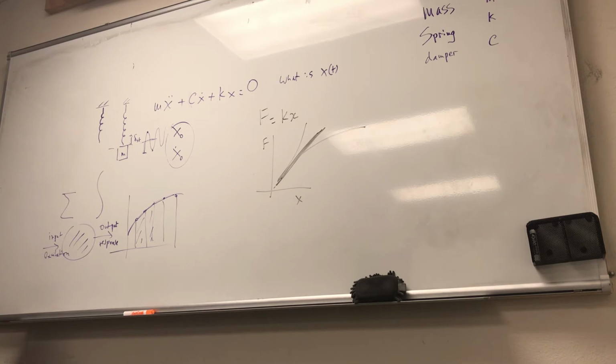Well, the first one is you can maybe take the anvil here and the frame and just use it as one big block, right? So we call this the big mass M. And then it's sitting on top of what? Well, this is the anvil and the foundation block, this entire business, right? And then because you have soil here at the bottom, it makes sense that the soil would probably have a certain little spring, and you probably will have a little damping also.